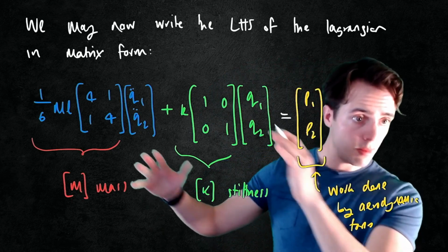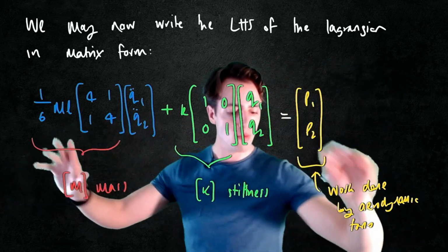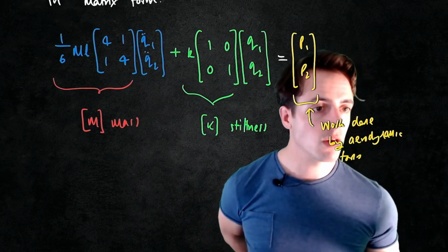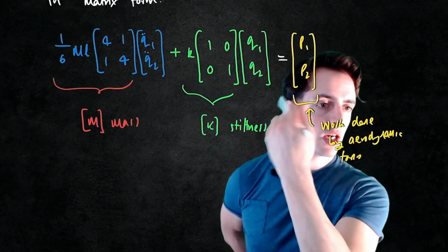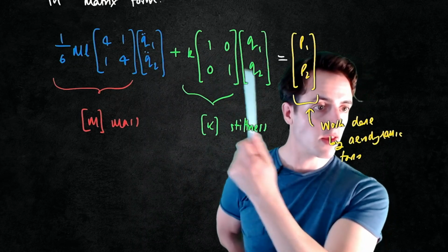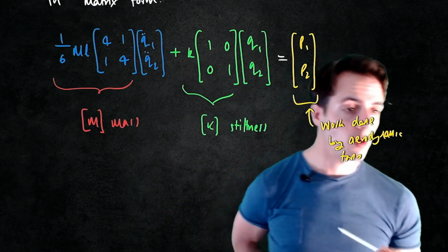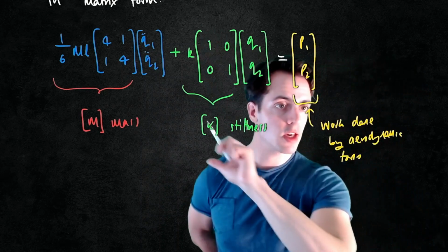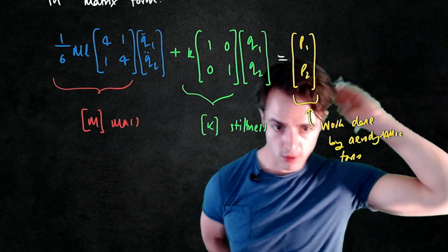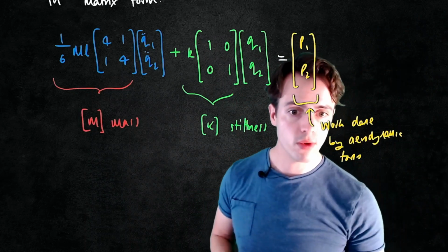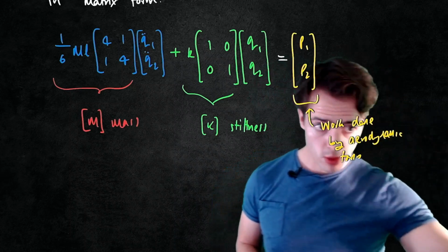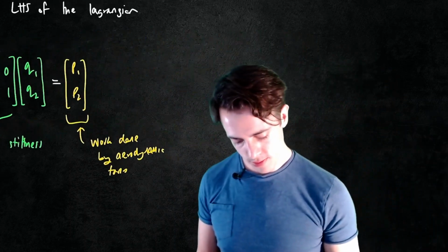So we've set up this left-hand side of this problem. We've done everything in a work energy formulation, so the units are going to be different to what they would have been from previous problems. We've got a stiffness here, but we're looking at the energy that's stored in this spring. We've got the kinetic energy in this one here, and then on this right-hand side, we're going to have the work done by aerodynamic non-conservative forces. So we still just need to work out these two things here. And for this, we're going to use a virtual work formulation.